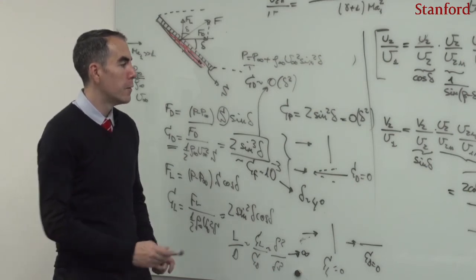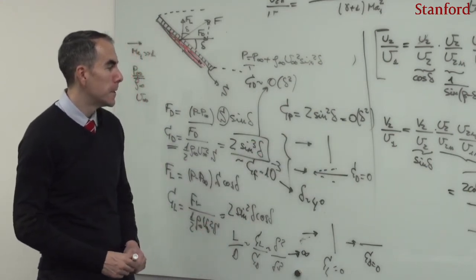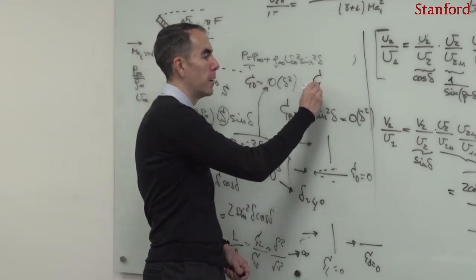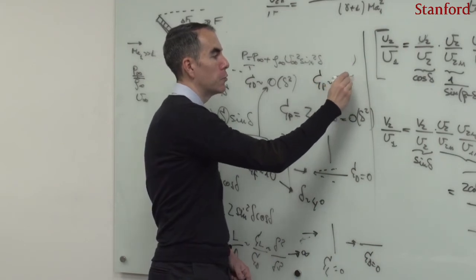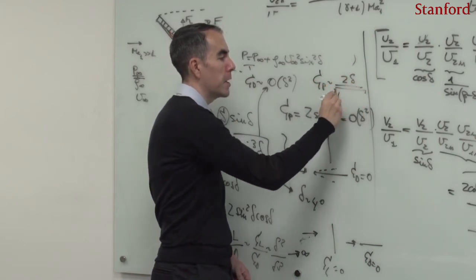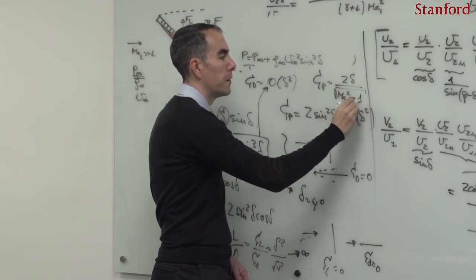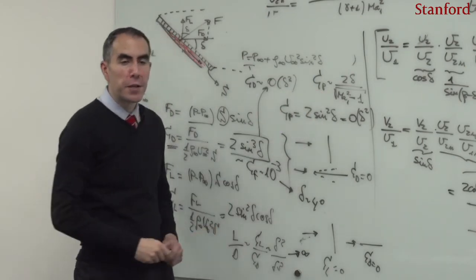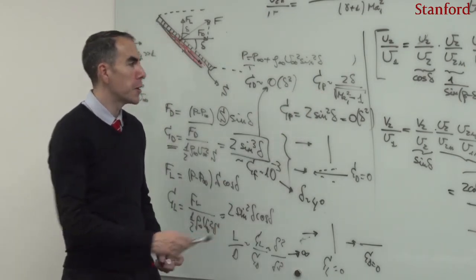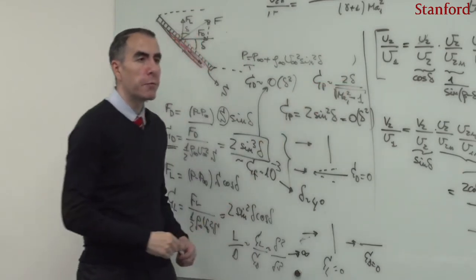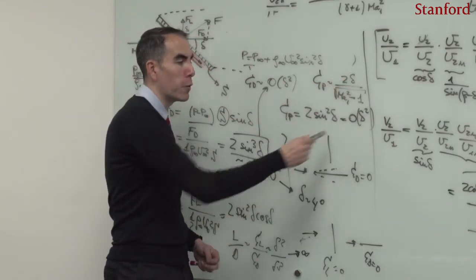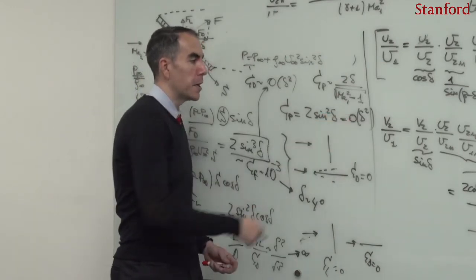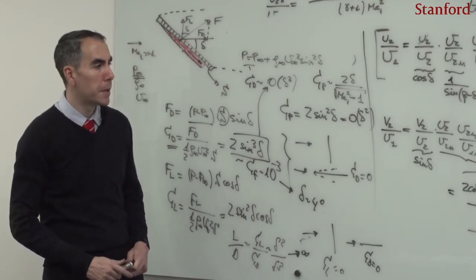If you recall, in the theory of linear supersonic aerodynamics, the pressure coefficient around a slender body goes like twice multiplied by delta and divided by the square root of Mach number square minus 1. So this is the pressure coefficient for a slender wing in supersonic aerodynamics. So this pressure coefficient goes linearly with delta, whereas in the Newtonian theory it goes quadratically with the angle, and that already tells us important details about the nonlinearities at play here.